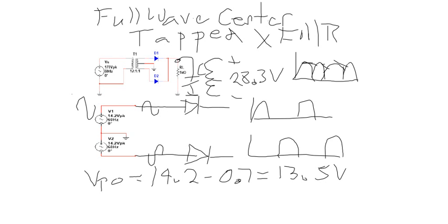So that ripple now is almost the same as the previous example. The peak output voltage coming out of the diode, still divided by the frequency, the resistor, and the capacitor. But we're only giving it half the time to die off in between pulses, so that cuts it in half, by a factor of 2.